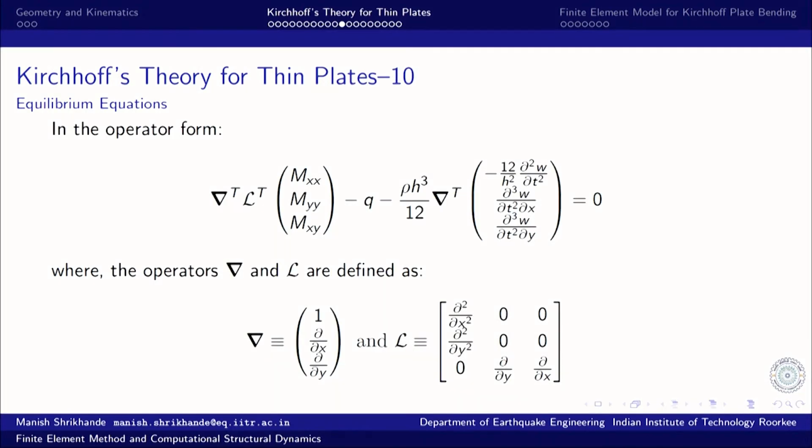In operator form, we can relate these moments and curvatures, moments and the applied forces, where this nabla is just the gradient vector and L is the differential operator involving curvatures, defining curvatures.